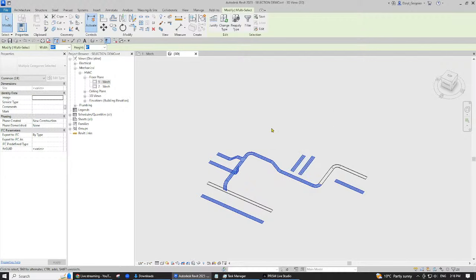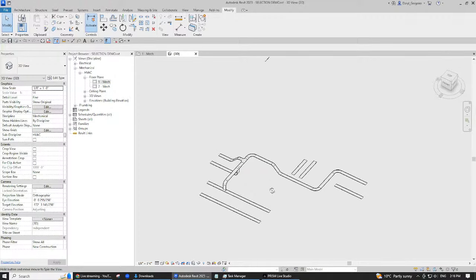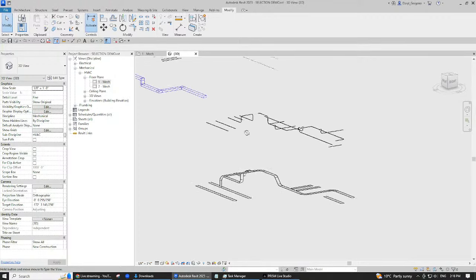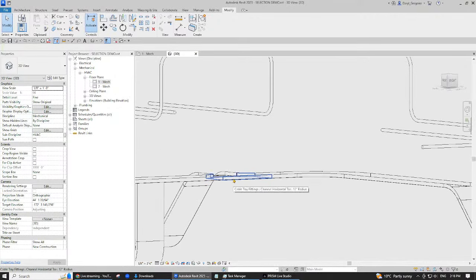And when I'm done with it, I can then pick on it and delete it or move it or do whatever I want with it. So selecting objects is a big thing. You can also use your tab key. So if there's a bunch of stuff, even really busy, all in one little spot where you can't really see, you can go tab, tab, tab, tab, and it'll cycle through different things in the area first of all. So the tab key on the keyboard will tab through.